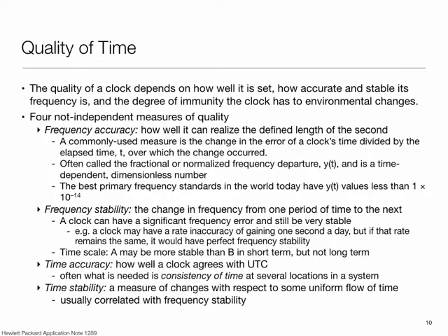And the other thing is, if frequency is unstable, then that offset, instead of moving away in a predictable fashion, behaves unpredictably. If the frequency offset was constant, then in principle you could learn it and compensate for it.